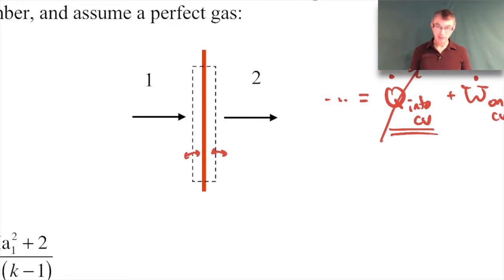So one of the things we'll show in a moment is that the velocity upstream and the velocity downstream are significantly different. And again, because the shock wave is so thin, you get large velocity gradients. And we know that if you have large velocity gradients, you can have large viscous stresses as well. And so you can have large viscous effects, large thermal effects. Those both lead to irreversibilities. So even though it's adiabatic, it's not reversible, so it's non-isentropic.